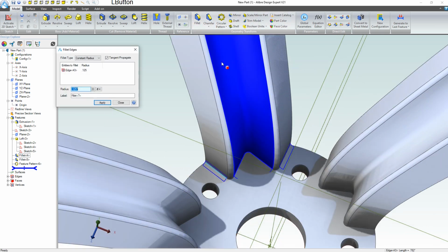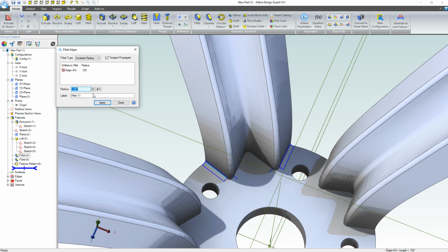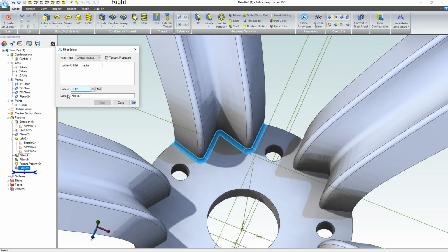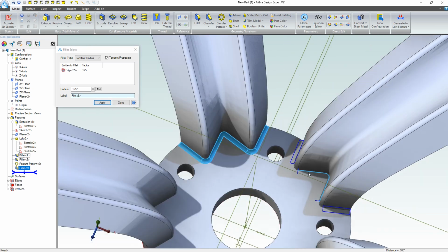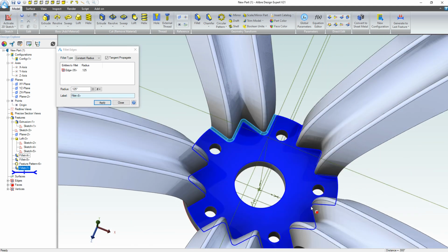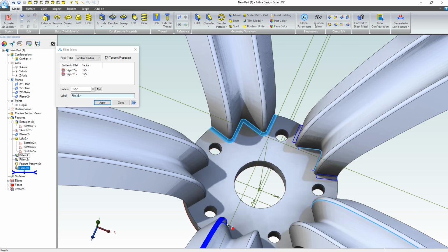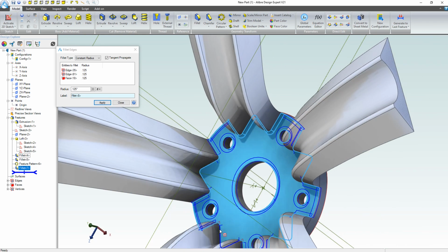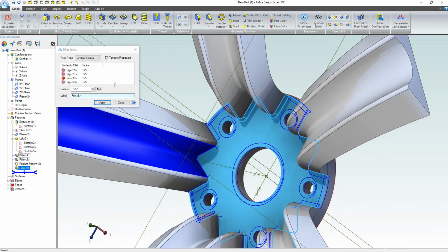Let's go with fillet. And yeah, radius of, well, maybe I can do a 0.125 because I'm taking a radius around the same radius here, so I think theoretically that works. Now, a wise modeler should save all their fillets till the end, but I'm a little bit excited right now.